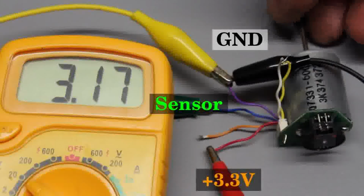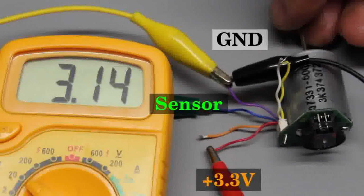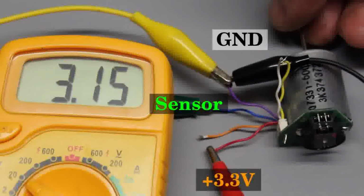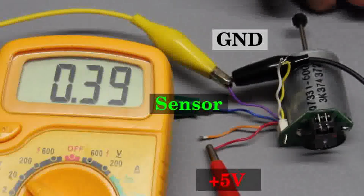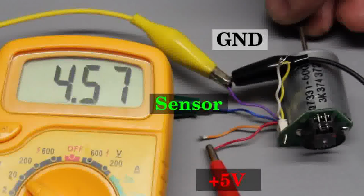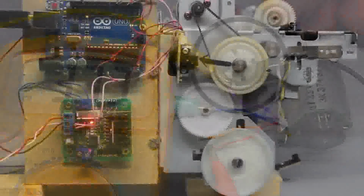At 3.3V, the sensor unit works fine. The voltage output varies clearly when turning the motor shaft by hand. I take the risk and connect the sensor unit to 5V and as you can see, it still works fine. That's how we can use transmissive optical sensors to detect motion. Mission accomplished.